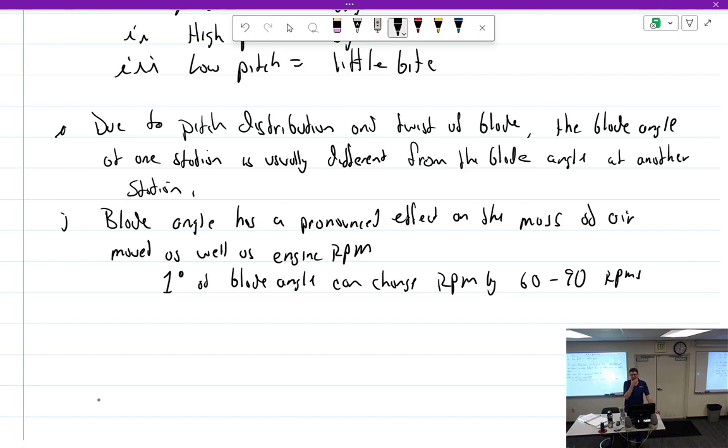Now, if you consider that the tachometer is, say, redlined at 2,700, or this one I'm working on is 2,550, and the RPM comes right up to 2,000. Would it not redline? It will not. A fixed pitch prop should never redline on the ground, brakes locked, ever.